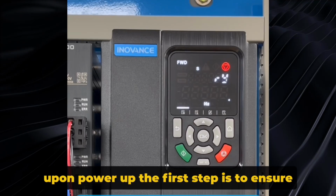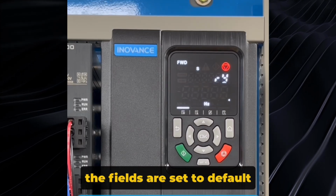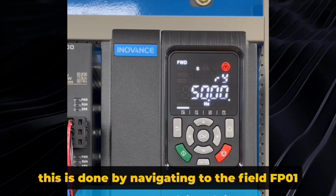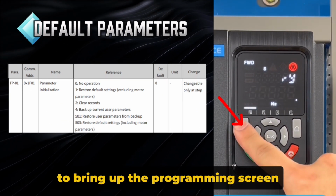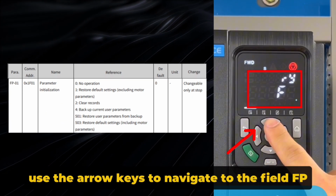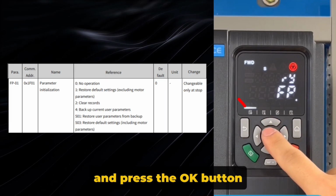Once we are all wired up, we can power on the drive and begin configuring the necessary settings. Upon power up, the first step is to ensure the fields are set to default. This is done by navigating to the field FP01. First, press the back button to bring up the programming screen. Use the arrow keys to navigate to the field FP and press the OK button.